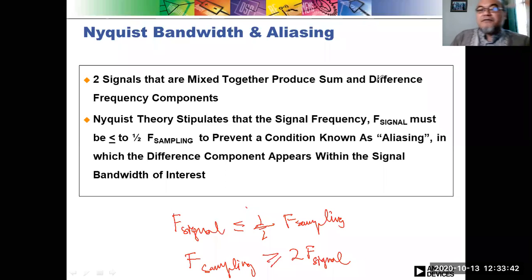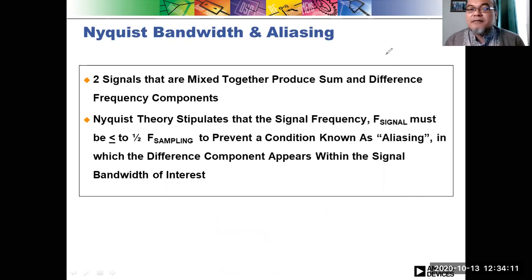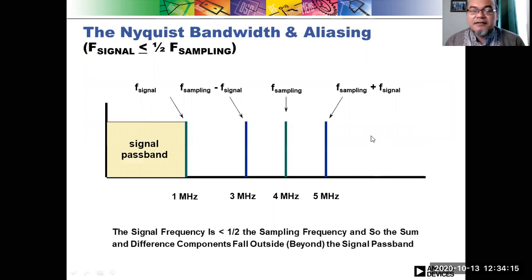Whenever you do a measurement experiment, you have to sample at 2 times the maximum frequency in the bandwidth of your biomedical signal. It cannot be smaller. Of course, this is the minimum criteria. If you want better performance, sample more: 4 times, 6 times, even 10 times. The more, the better. But of course there is a drawback, that it needs higher energy.